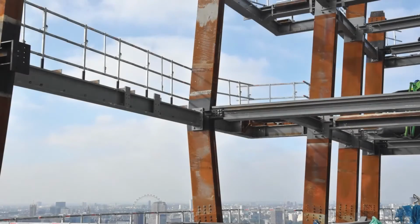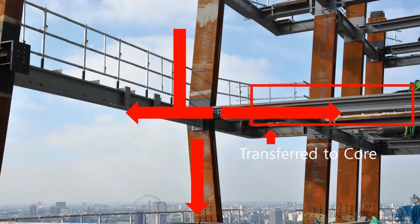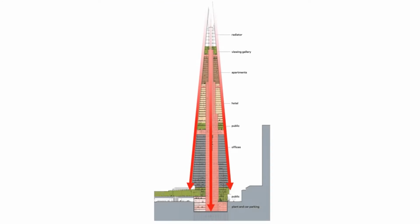Therefore, the changes of direction generate substantial horizontal push and pull forces. These tension forces are transferred to the core by horizontal steel struts. The horizontal load moves from the perimeter column to the core, and the core load is transferred to the foundation.